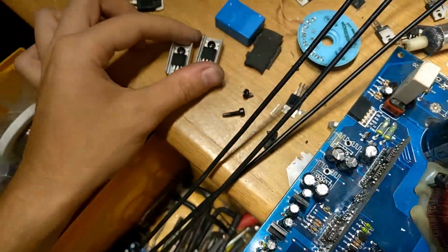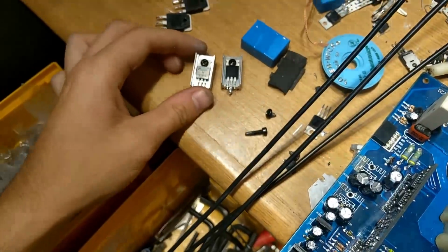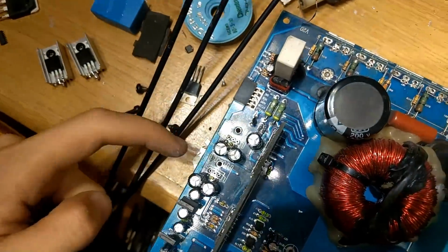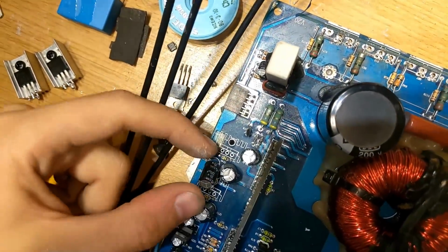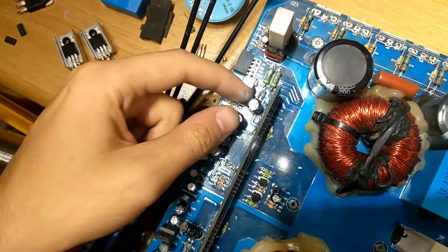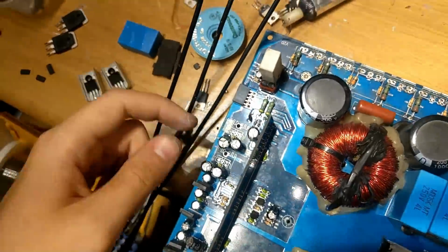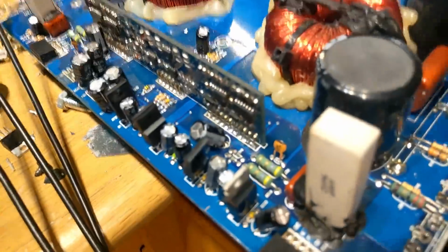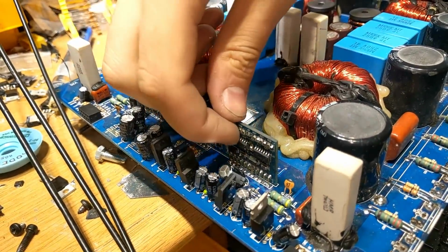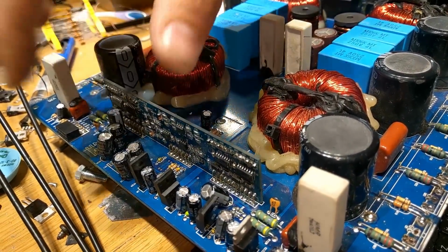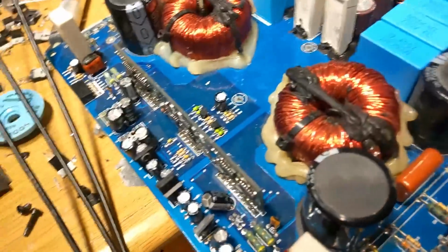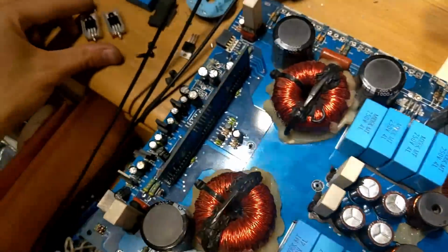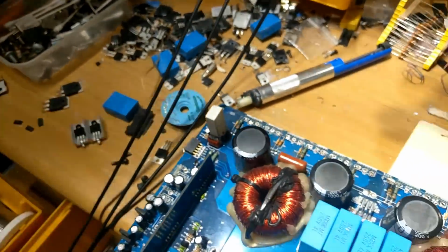We need to replace both 12 volt regulators, these KA7812s, because obviously they failed, having been shorted to positive rail, so they go in there. I will need to check out a bunch of these other capacitors and stuff around this section, make sure that nothing else got damaged when it took a hit with the positive rail, but I think we're going to be okay. I have already replaced all 4 drive ICs with the IRS21844S. That's all good to go. So once I have rerun the trace from the auxiliary rail and replaced the 12 volt regulators, then I'll be ready